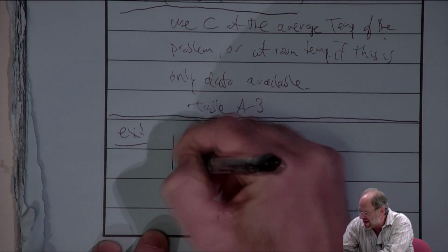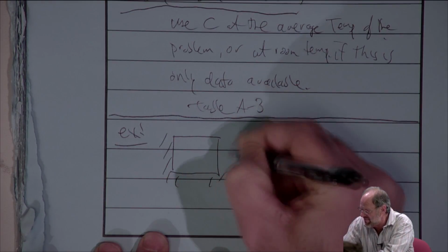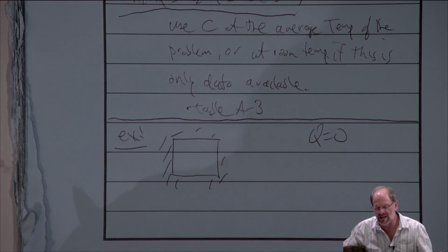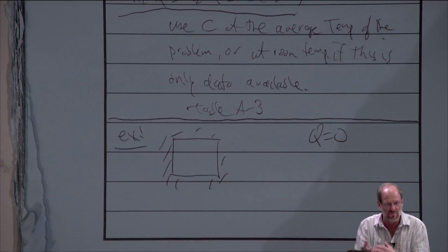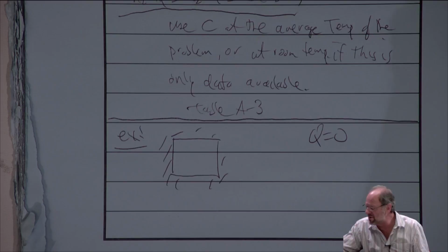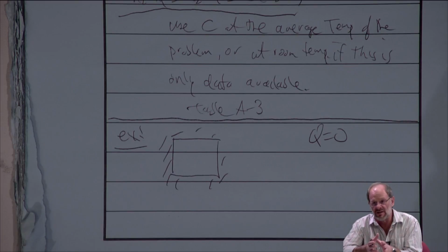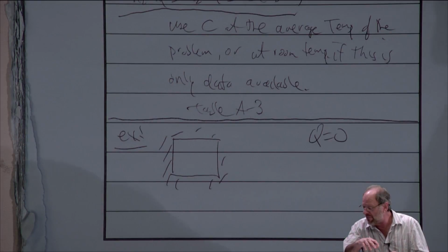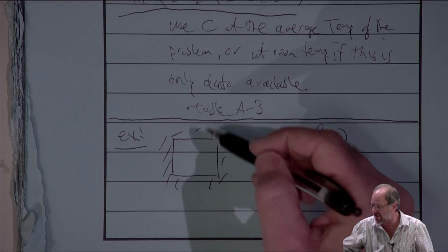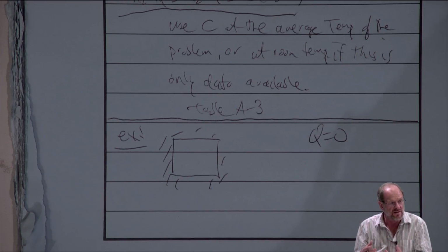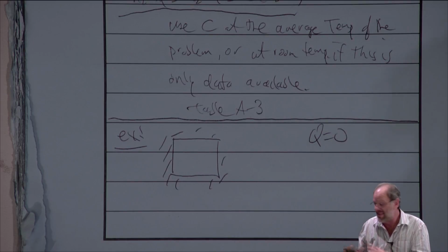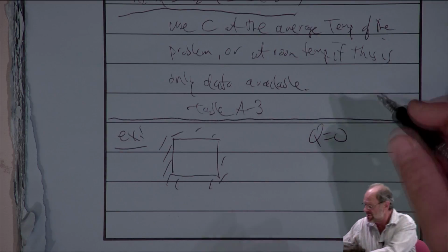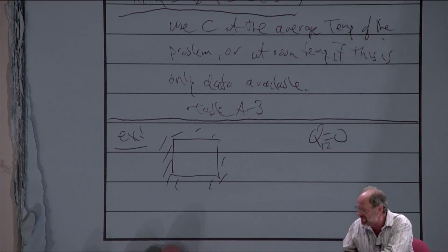All right, so here's our example. Now, it tells us that it's insulated. So that means that there's no heat transfer. Now, you may say, well, wait a minute, there has to be heat transfer. The water's picking up heat from the iron, the iron's losing heat to the water. But the iron and the water are both inside the system. The amount of heat lost by one is immediately gained by the other. It's a net washout. When we talk about heat transfer or work, we have to identify the boundary of the system, and it's that entire container that's the boundary. There is no heat transfer across the boundary. That's the only heat transfer we deal with in a problem like this. We are never concerned with internal heat transfer. So Q12 is clearly 0.